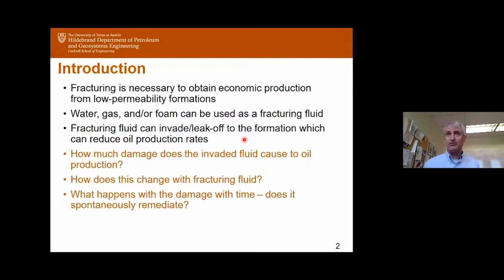Okay, so why does it make a difference which fracturing fluid you use? The main reason is it can invade or leak off into the formation, and this could reduce our initial oil production rates, maybe even our final oil production rates. So what I'm going to talk to you about today is trying to understand what's going on with this fracturing fluid. I'm going to talk about experiments, not models. We'll do a little bit of modeling, some theoretical, some numerical stuff later on. But the main thing is driven by experiments. And basically the questions are: how much damage does this invaded fluid cause to the oil production? How does this change with the fracturing fluid? And what happens with the damage in time?